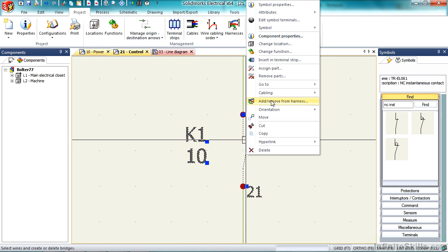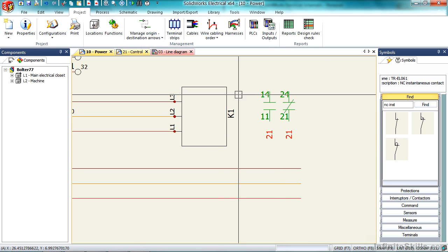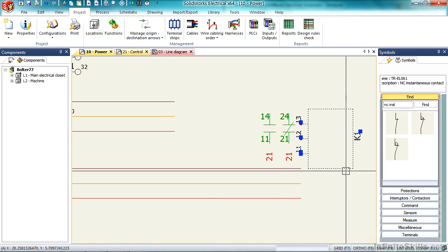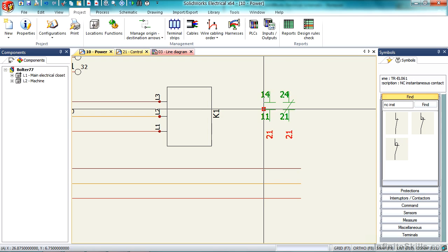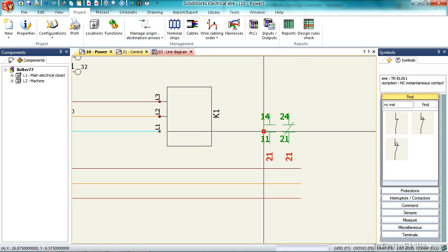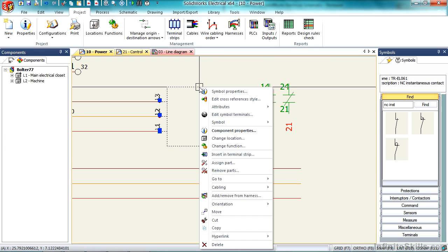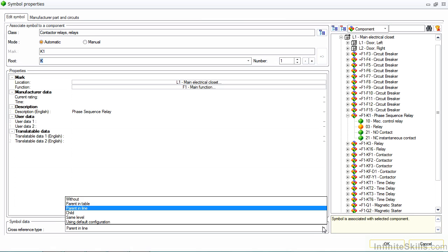To control the display of these objects on the schematic, go back to the sheet where you have the cross-reference symbol, and you'll notice that it will actually move along with it. It'll stay in the same region as the symbol. You can independently move the cross-reference symbol, but it will always stay relative to the original parent symbol. You can display this cross-reference symbol in many different ways.